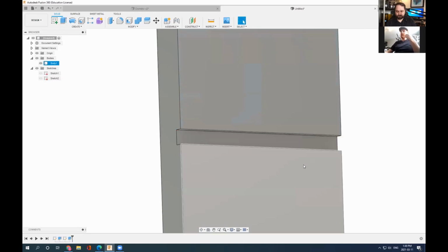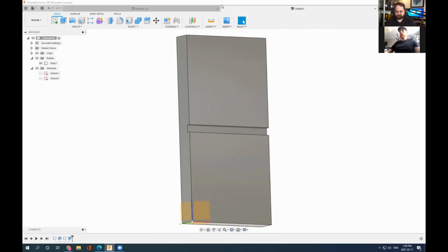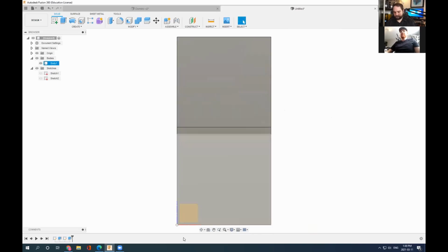So then we hit OK, and we now have that secondary feature, the defining feature of the center line, being created. So again, a reminder that now we're zoomed in and we're looking just at that, but maybe we want to check out our whole domino, or almost domino, let's call it. You can just click on that and you'll see the full perspective. If you want to look at it straight on again, you can click on front, and we're back here. We now can tell that we have our center line that is being pushed in. We now have 2 sections that can be highlighted.